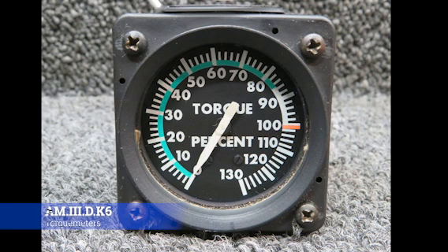Generally, the transducer is used to transfer the oil pressure to an electrical signal to be read on the flight deck, but you can get some of these older analog gauges. Nowadays on a modern digital display, it's just going to be a number that comes out. The readout's typically in foot-pounds of torque or percent of horsepower. The torque meter is very important because it's used to set power settings, and the instrument must be calibrated at intervals to assure its accuracy, which will be part of your heavy checks.